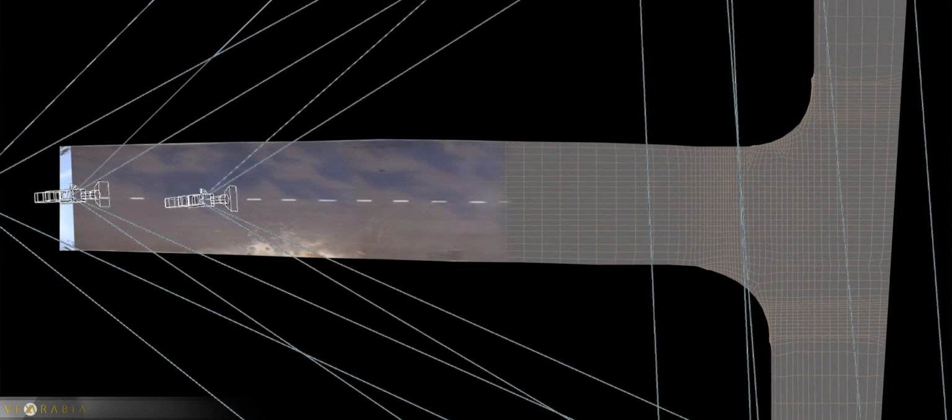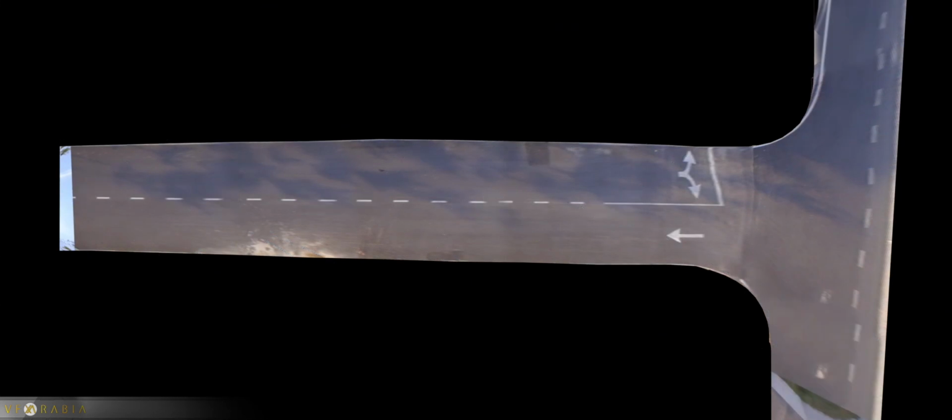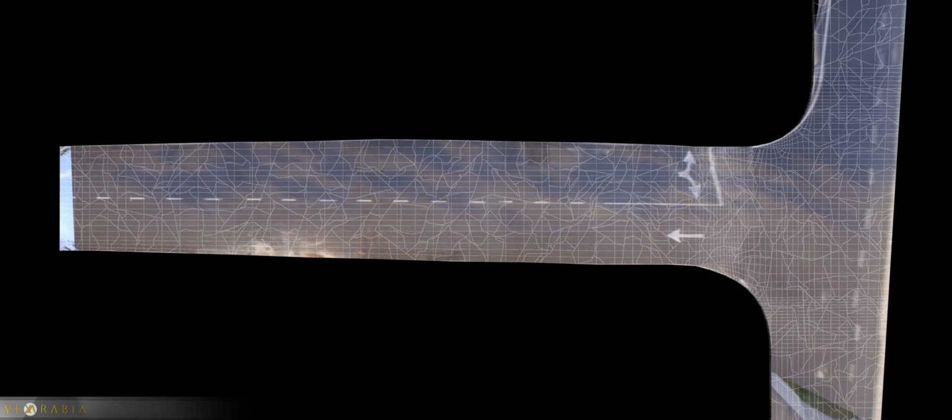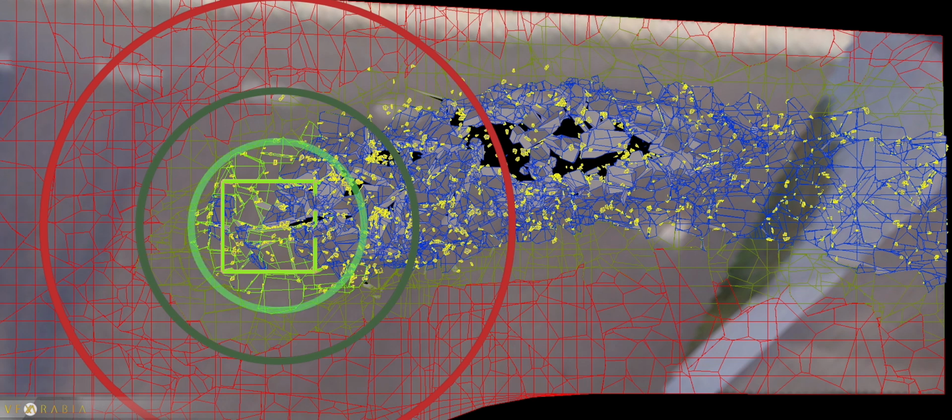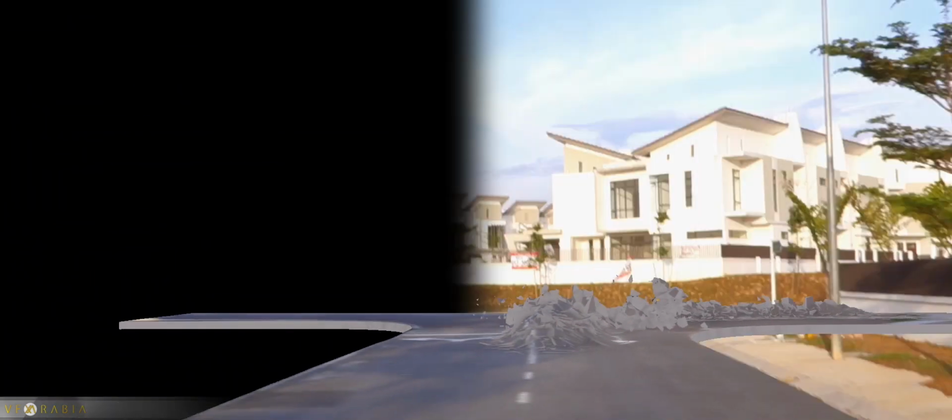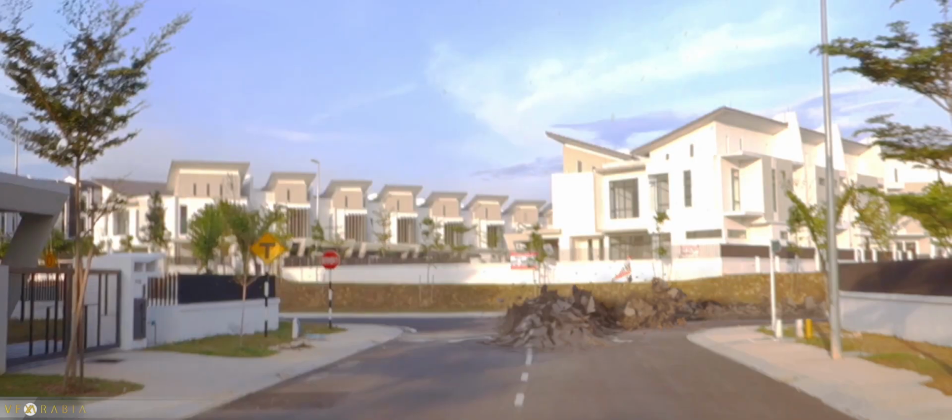I received a couple of emails asking me about the technique I used to achieve the mapping for the road in my video under the title Road Destruction Glanmary, especially after posting the breakdown video. And my answer was by writing a script that automates the process of creating camera map modifiers and a composite map for the road or the desired object. But it sounded harder than it really is.